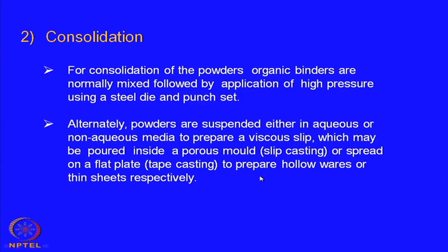These tapes are basically a composite of some polymeric material in which very fine ceramic particles are dispersed. The tape is flexible to start with, and then you heat it to high temperature, when the volatile compound or polymeric binder evaporates, and you get a stiff, very thin ceramic. That is another technique by which thin sheets can be prepared.